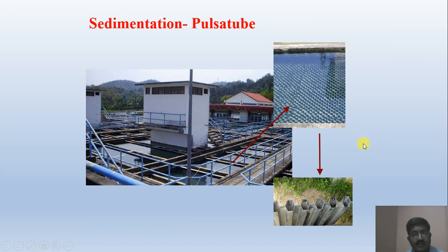There are also tube settlers, tube-like structures. You can see these provided in the water, and because of these tube settlers, the particles settle earlier.